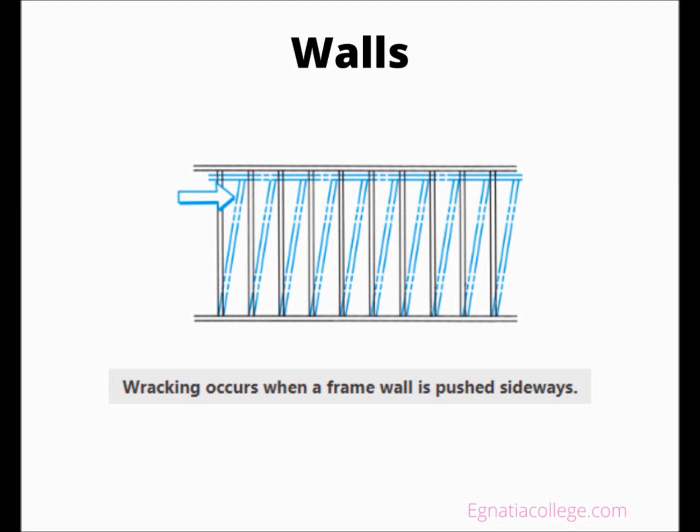But in high seismic areas, nailing is typically specified by the structural engineer. Sheet S7.1 has a shear wall schedule that includes information on sill plate thickness, nailing schedules, and whether structural panels are required on one or both faces of the wall. This schedule also calls out anchor bolt spacing and alternative connection methods.